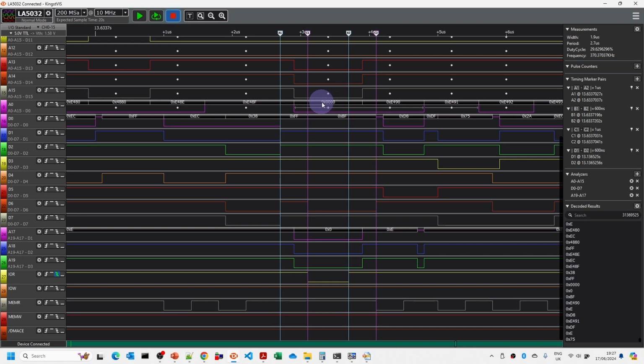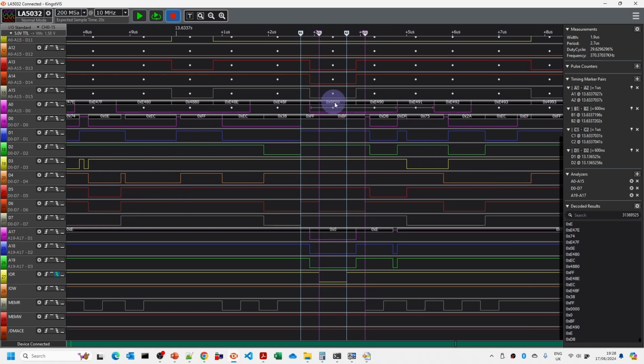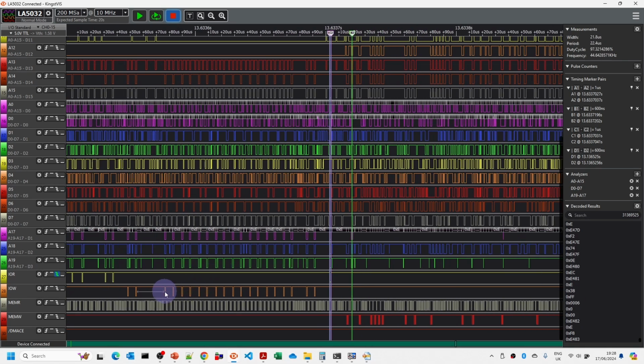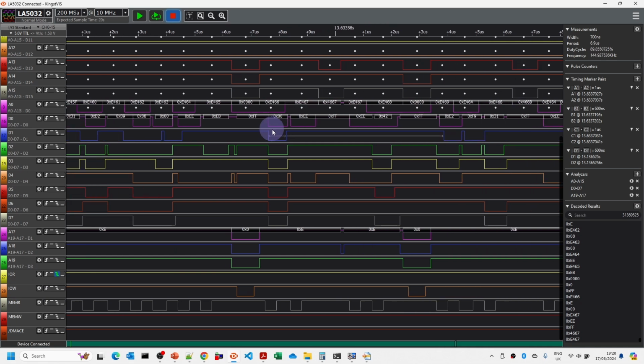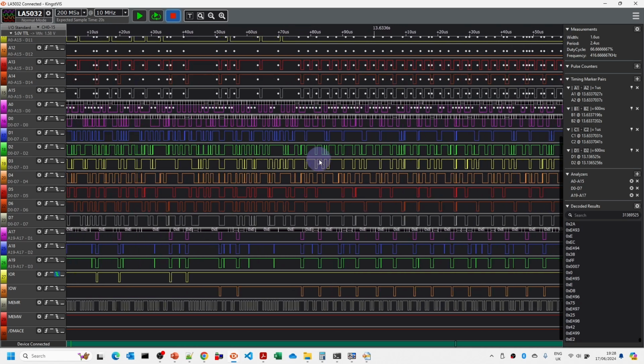And what we can see here is it's reading 0000 and it's getting BF back. Now, if we go back a little bit earlier, so this is the 0000, 4 zeros. And what's the value that we actually wrote to that last? If we go back here, we should be able to see that, there we go, we actually wrote an IO write there, FFF, and there'll probably be another write as well. So this is the least significant byte and most significant byte. They've both been written as FF.